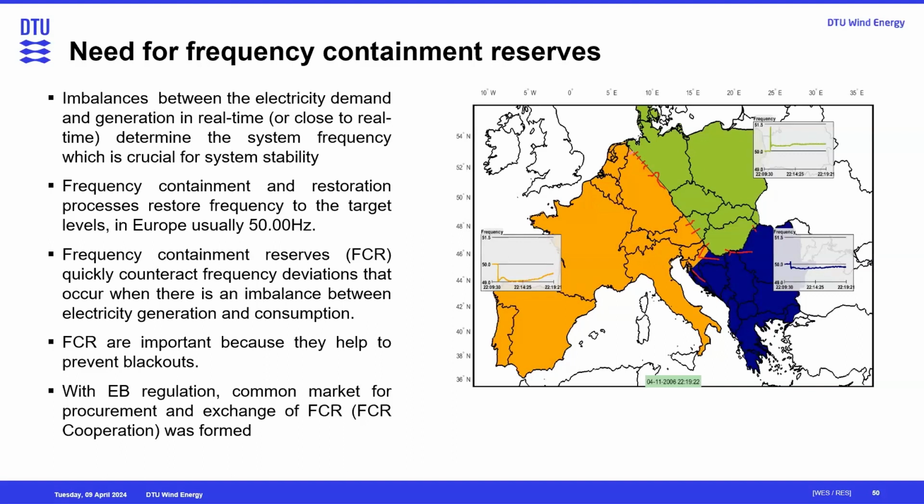Then they opened the bridge. As a result, the first transmission line got overloaded because the power started flowing in other routes, and it got disconnected. That overloaded another line that got disconnected.